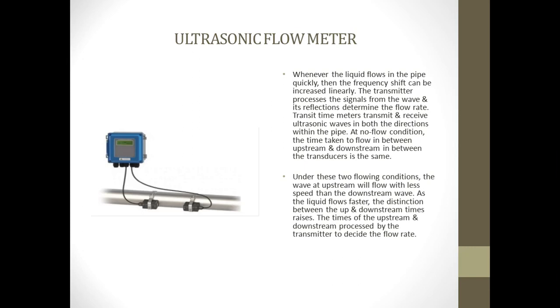The operating principle of this type of instrument is based on the apparent change in the velocity of propagation of small magnitude pulses which travel through a fluid at a definite velocity, normally the velocity of sound relative to the fluid. If the fluid itself has a velocity, then the absolute velocity of pressure disturbance propagation is the algebraic sum of the two.